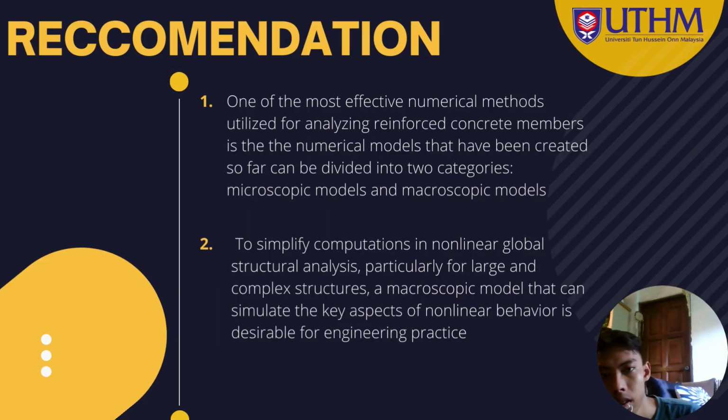For the recommendation, one of the most effective numerical methods utilized for analyzing reinforced concrete members is numerical modeling. The numerical models that have been created so far can be divided into two categories: microscopic models and macroscopic models. To simplify the computation in nonlinear global structural analysis, particularly for large and complex structures, macroscopic models that can simulate the key aspects of nonlinear behavior are desirable for engineering practice.